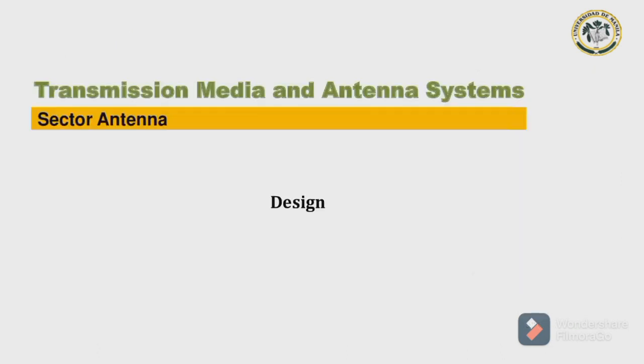Next, we will proceed to the design of sector antennas. A typical sector antenna is depicted by the picture shown. At the bottom, there are RF connectors for coaxial cable and an adjustment mechanism. For its outer placement, the main reflector is produced from aluminum and all internal parts are housed in the fiberglass radome enclosure to keep its operation stable regardless of weather conditions.